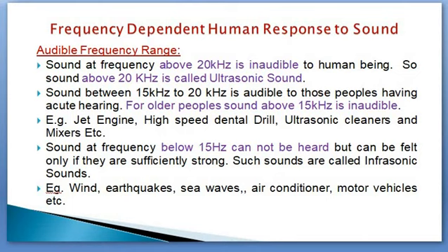Now these subjective responses we are going to connect with some physical parameters which are measured with respect to sound, known as frequency and sound pressure. Firstly, the frequency dependent human response to sound. From research in the laboratory as well as surveys, it is observed that sound at a frequency above 20 kHz is inaudible to human beings. So sound above 20 kHz is called ultrasonic sound. Humans are generally not able to hear ultrasonic sound.